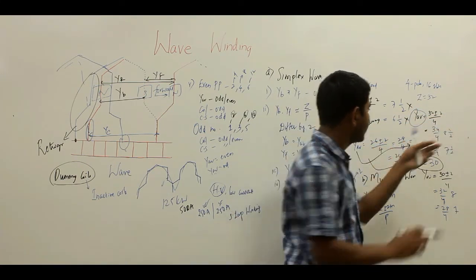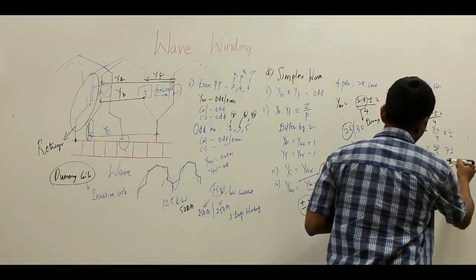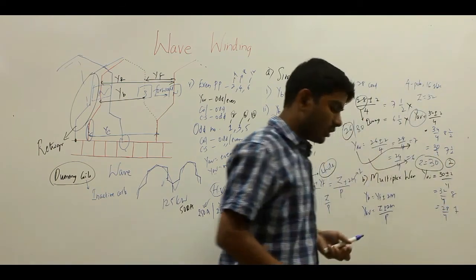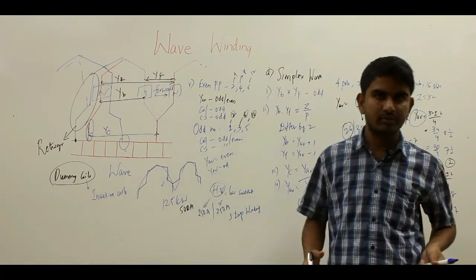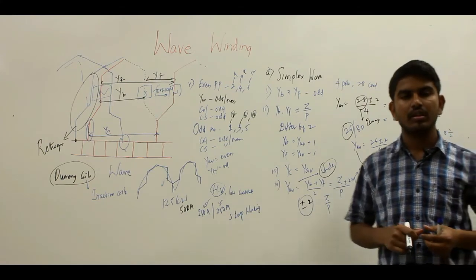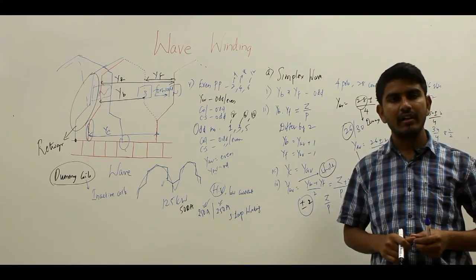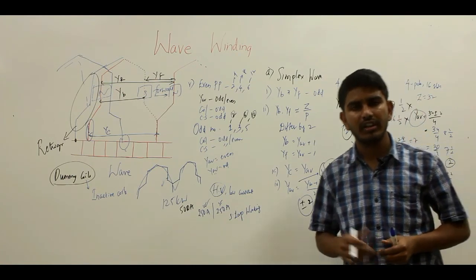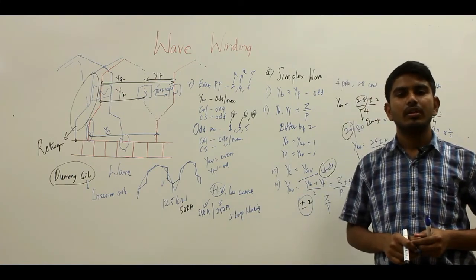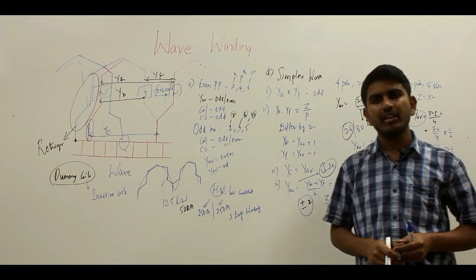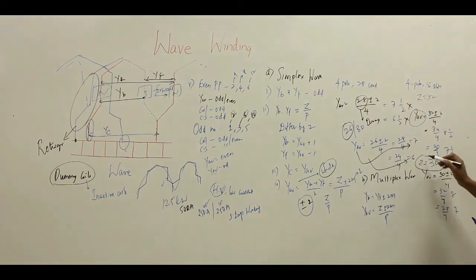And these two conductors are causing a problem now, because whenever you go to the armature winding shops, there will be already standard armature punchings, and they may not be according to your requirements of the winding. So according to the requirement of your winding, you need only 30 conductors.